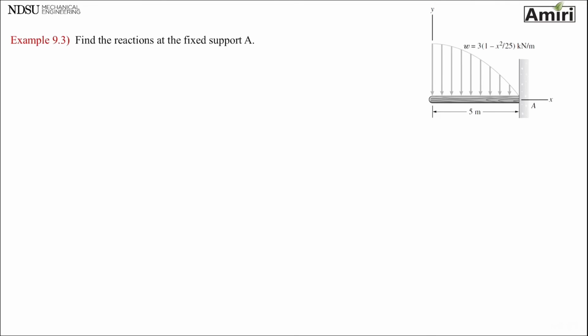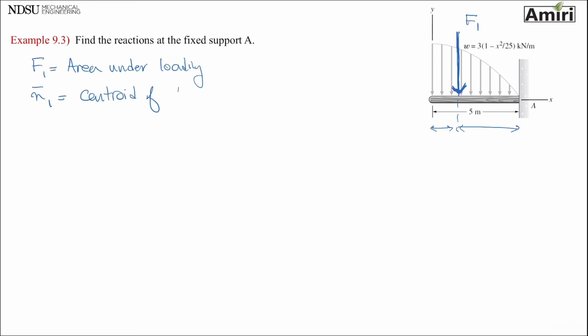So I have to replace this load by a force of F1 and find its distance to point A or to Y, doesn't matter. And remember, F1 is area under loading, and X bar is centroid of area.